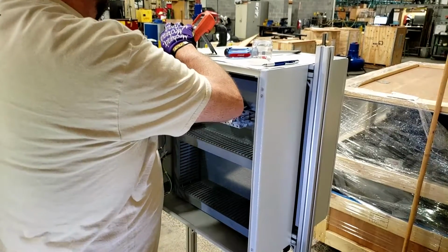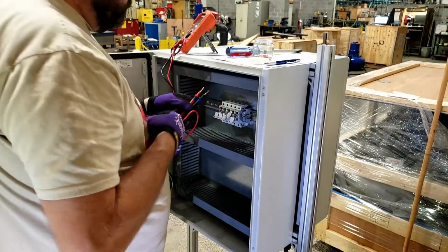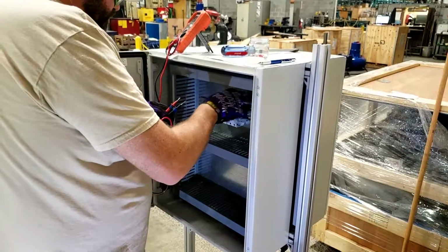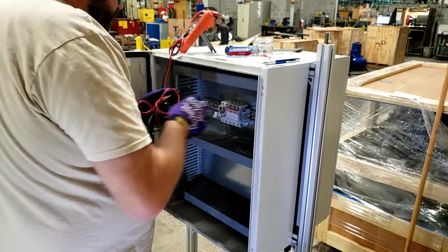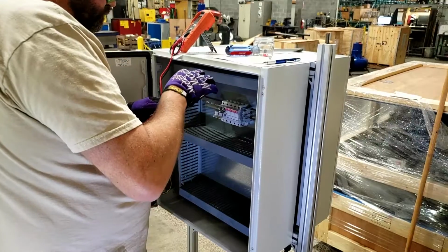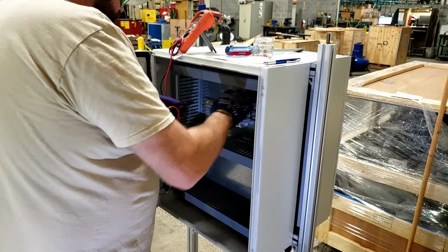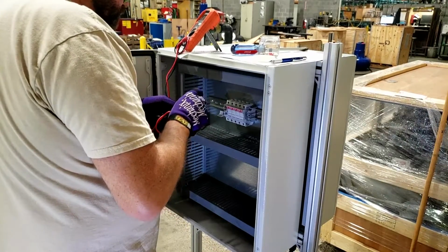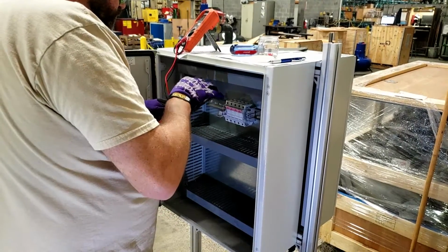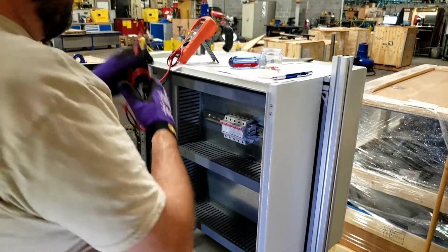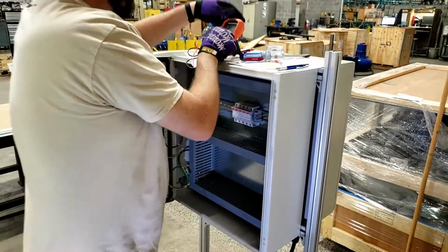Please note that if you choose to not perform the continuity test at the panel or directly in front of the panel, you must close the panel and lock at least one of the locks on the door. Fuse is good. All fuses have been checked. Bad fuses have been replaced.